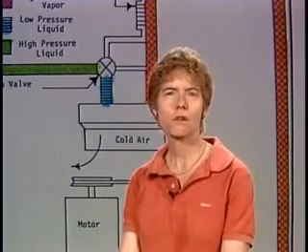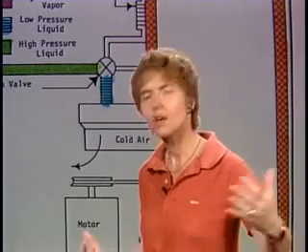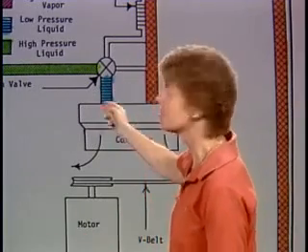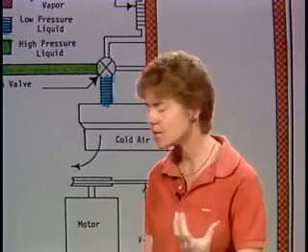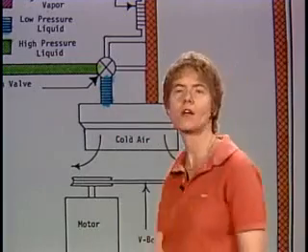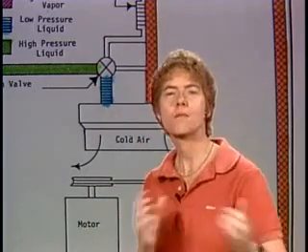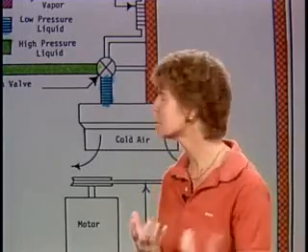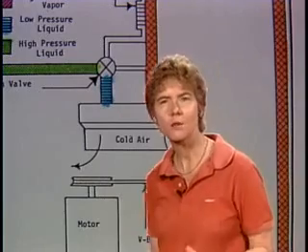So the condition of the refrigerant as it enters the evaporator is what? Liquid or vapor coming into the evaporator? It is a liquid. Is it a high-pressure or low-pressure liquid? It is a low-pressure liquid. And as the Freon leaves the evaporator, now is it a liquid or a vapor? Now it's a vapor. Is it a high-pressure or low-pressure vapor? It is still low pressure, but now it's a vapor instead of a liquid.